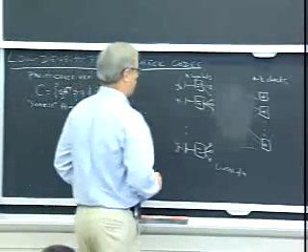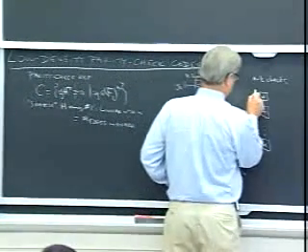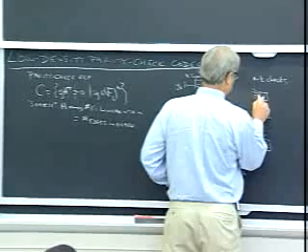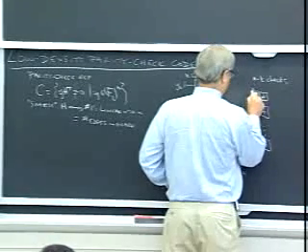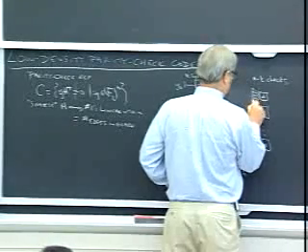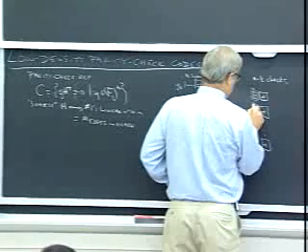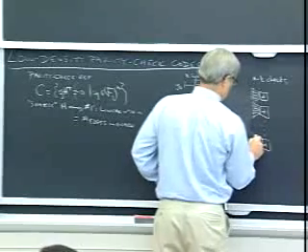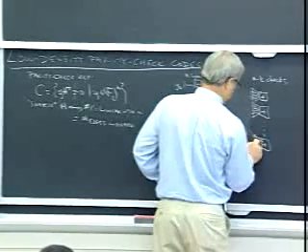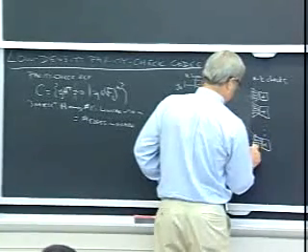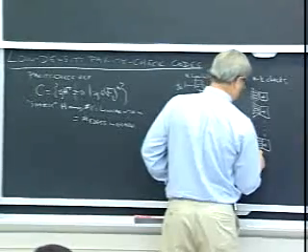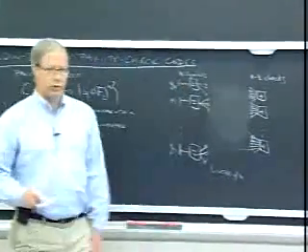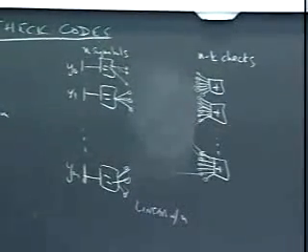Each symbol is going to participate in the same number of checks. Each one is going to have the same degree. So that's why in graph terms it's regular. Each one of these checks, we're also going to say has the same degree. So this was basically the way Gallagher constructed codes. Regular, we'll later see if there's an advantage to making these degree distributions somewhat irregular. But this is certainly the simplest case.